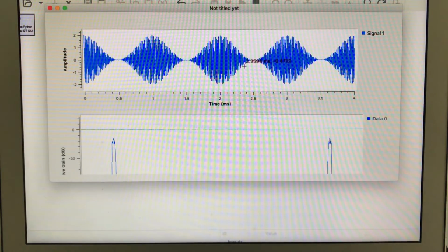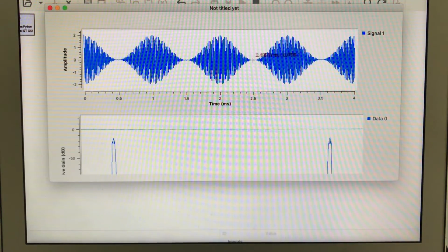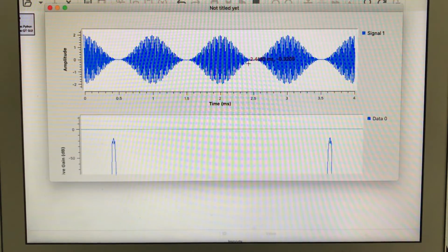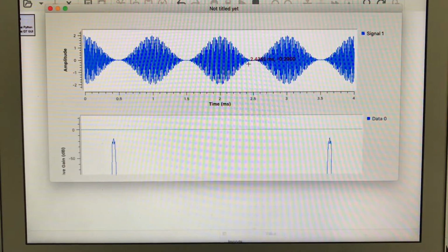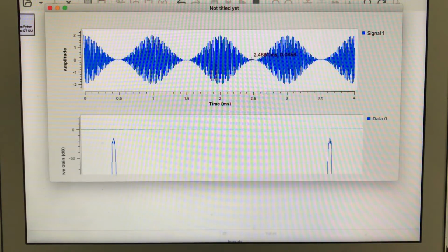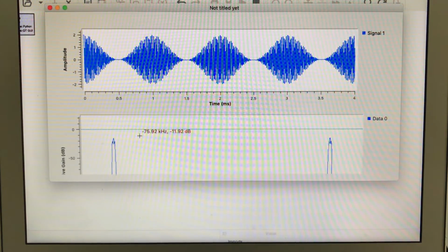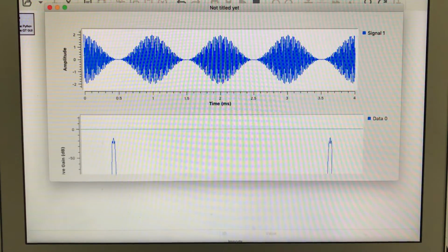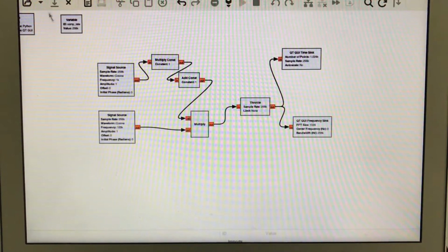So this is 100% modulated signal. As you can see, there's nothing here. You can do maximum value minus minimum value divided by maximum value plus minimum value, Vmax minus Vmin over Vmax plus Vmin. That should give you a value of 0 here. So now I'm not seeing that picture clearly. So what I'm going to do a few things.